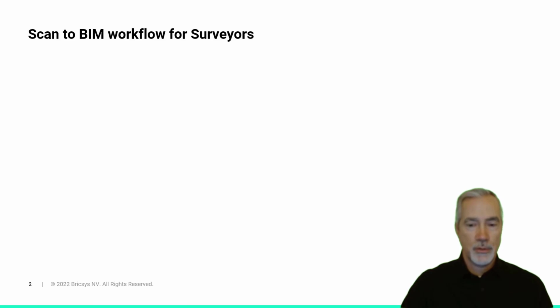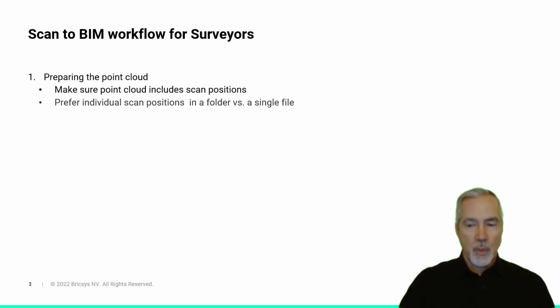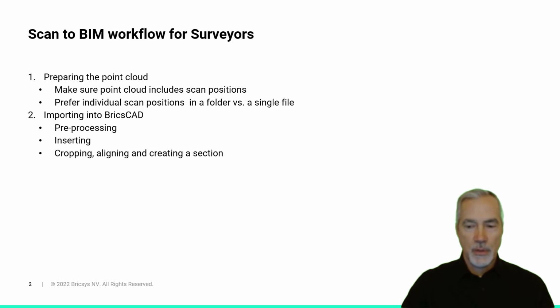My presentation will introduce you to the flexibility BricsCAD BIM provides for importing point cloud data and modeling tools for converting point clouds into BIM models. We begin with the point cloud. Once a project is scanned, the point cloud can be shared in many common formats that BricsCAD can import. Receiving individual scan files is especially helpful for the interior spaces first modeling method. No extra software is required to bring a point cloud into a BricsCAD BIM drawing file. Once inserted, you are ready to model, and the point cloud can be manipulated for better viewing and modeling.